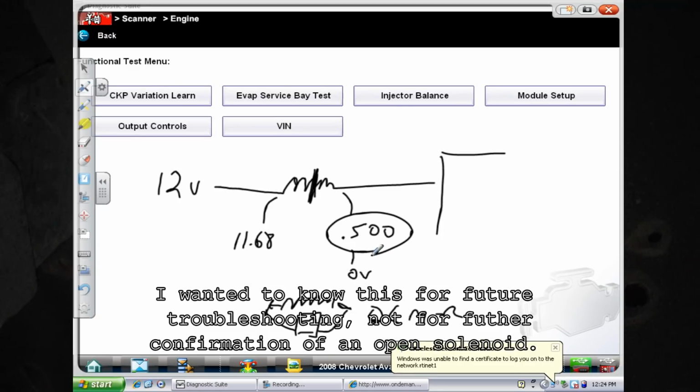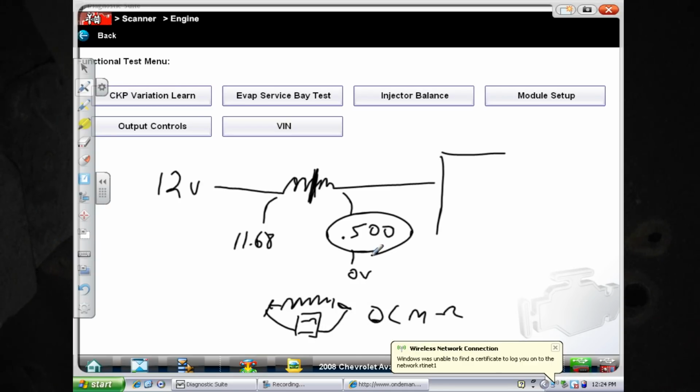Could have been that ghost voltage we were talking about earlier. I don't think so, though. We were, no, it's definitely possible. That's exactly what we were reading, is from the room, with that solenoid being open. And then when we grounded it with the driver, we're pulling any of that to ground. It could absolutely be that. That's a good point. Another thing it could be is that 500 millivolts could actually be coming from the computer in some type of bias voltage.